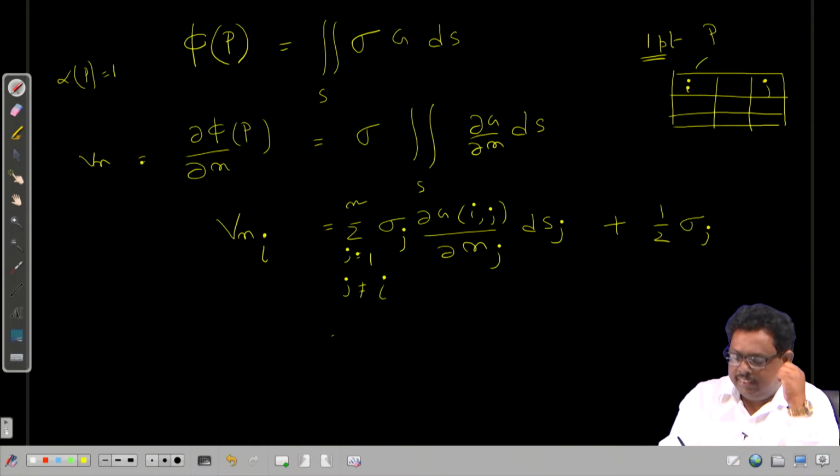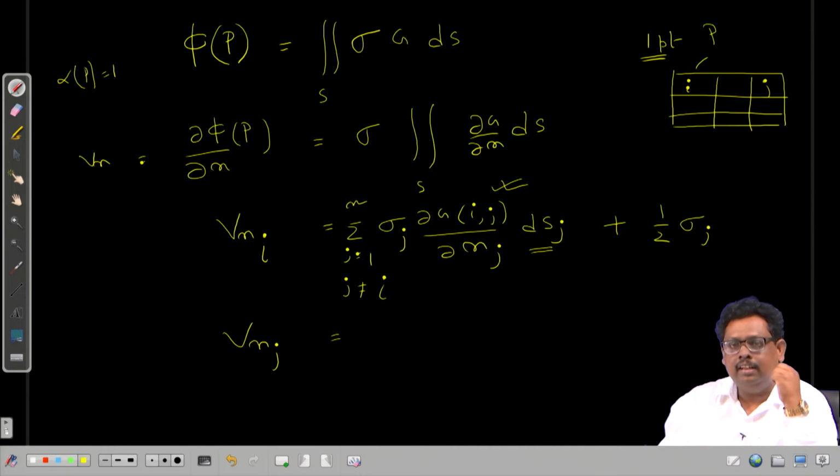So, then it is very simple. In case of a one point Gauss quadrature rule, I am taking the functional value at the centroid of the panel and then I multiply by the area, right.